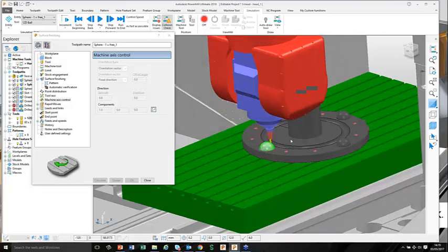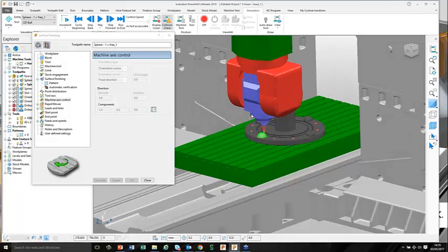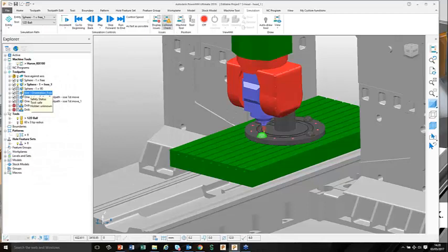Okay, so that's really all there is to fixing the head in the correct orientation. Now, we're using 0 and 90 degrees. Obviously, you may have a part at a strange angle. There's nothing stopping you going to the dynamic machine control, just twisting the head around, measuring the angle, and then putting the offset angle in there in exactly the same way. Okay, so that's fixed direction.